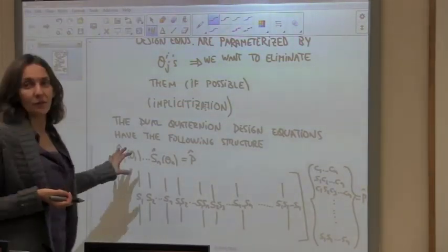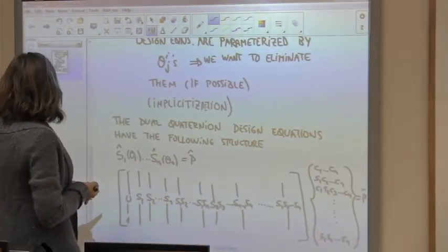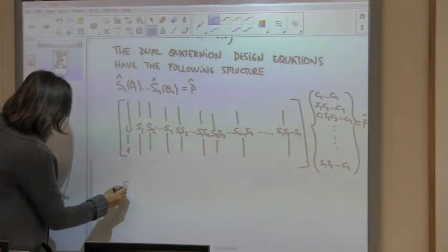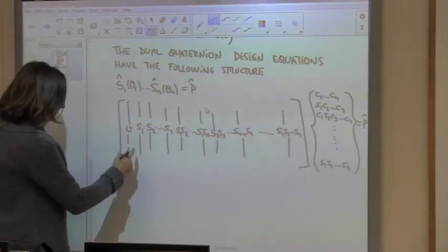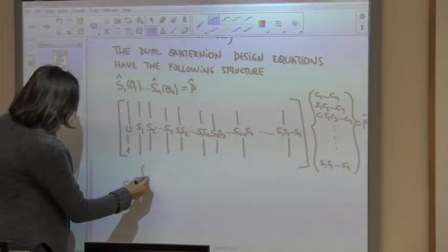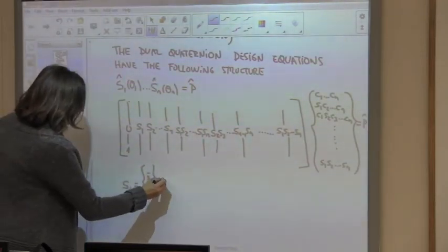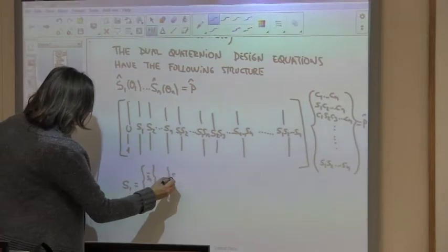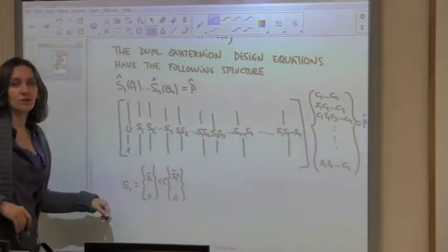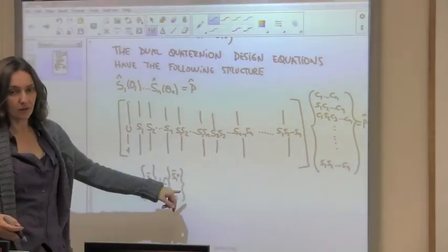So bottom line is we cannot eliminate this simply. We wish, but let me show you what these are. The S1 that we put here is not the Plücker coordinates of this; it is an 8-dimensional entity. So what you have is the direction, and then a 0 as the number, plus epsilon, the moment, and a 0. This is what is called a pure dual quaternion, when you have the zeros in the scalar.